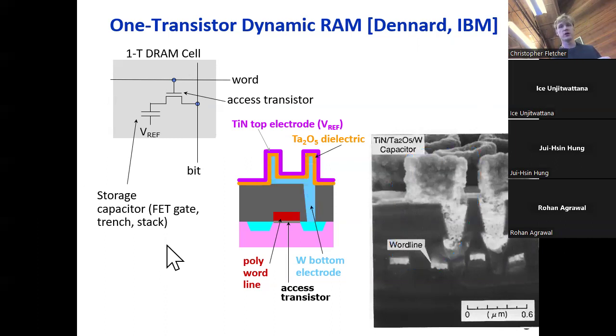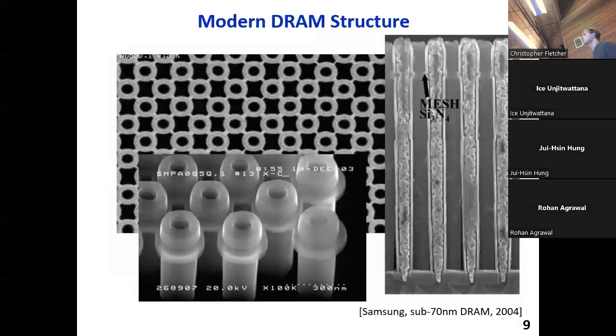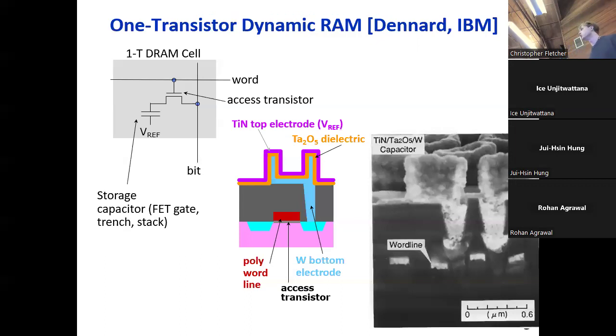Okay, great. So here's a DRAM cell. This is what DRAM cells look like nowadays. Old school DRAM cells are these bulky shapes. And again, the design philosophy with DRAM was let's go as dense as possible. We want the access to be fast, but we're going to prioritize density over access speed. So it started looking like this picture on the right, but this was still not dense enough. This shape is bulky. It's difficult to cram more of these structures in per unit area.